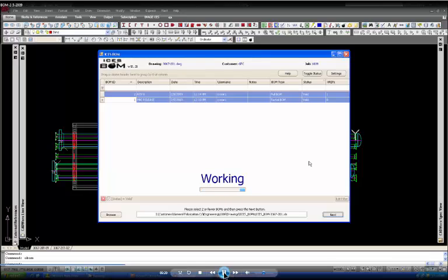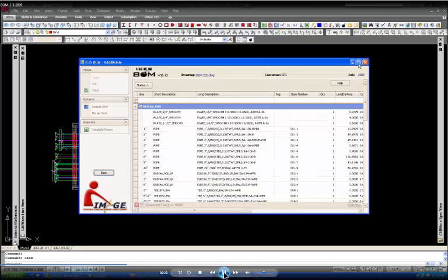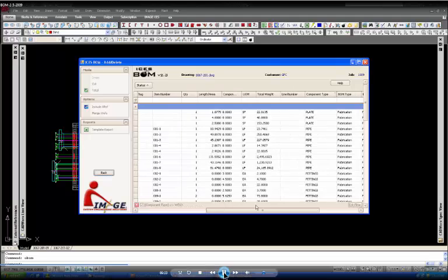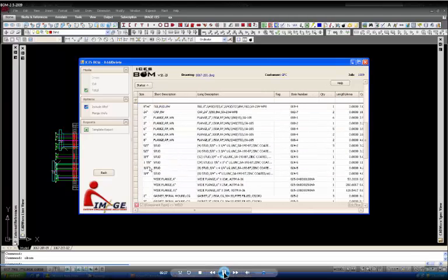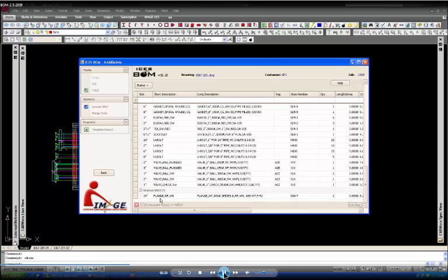Now this add delete sheet is basically like a bill of materials report, but it compares these two snapshots, and it comes back telling you add this many feet of pipe, this many flanges, and so on, and delete this many items, and that will make your old bill of materials that you released yesterday equal to what your model is today.